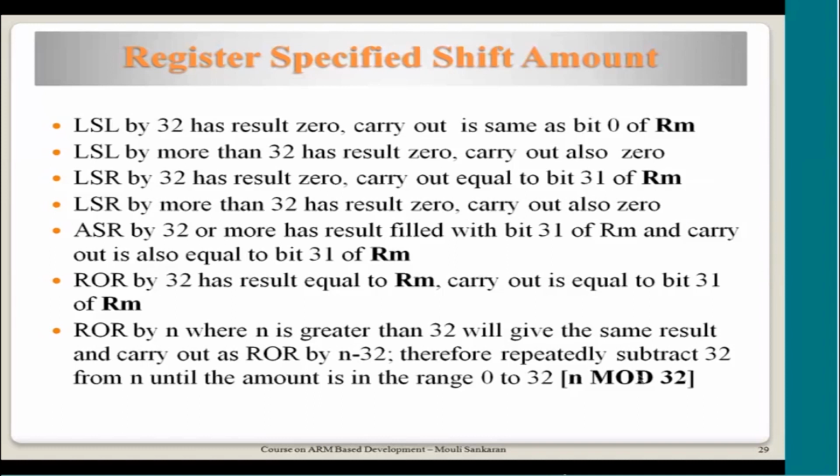Okay, maybe I should remove this n mod, because you may think that it will do only n mod. Actually no, please remove this n mod. It will do 32 times, and then whatever remaining bit is there, it will do the rotation and leave that value. It will be either all zeros or all ones based on the carry flag, if the MSB bit was set. Okay,